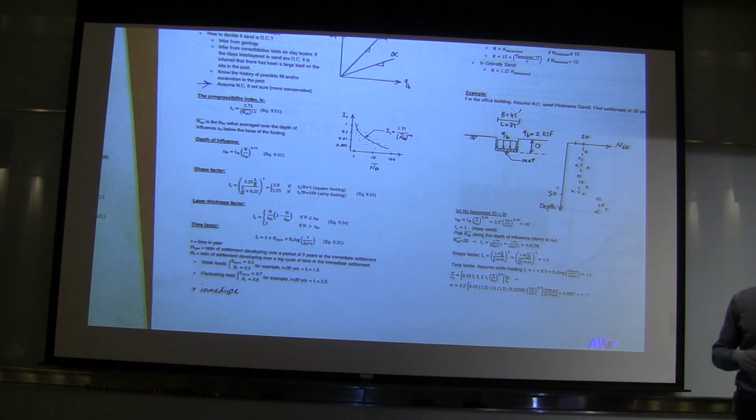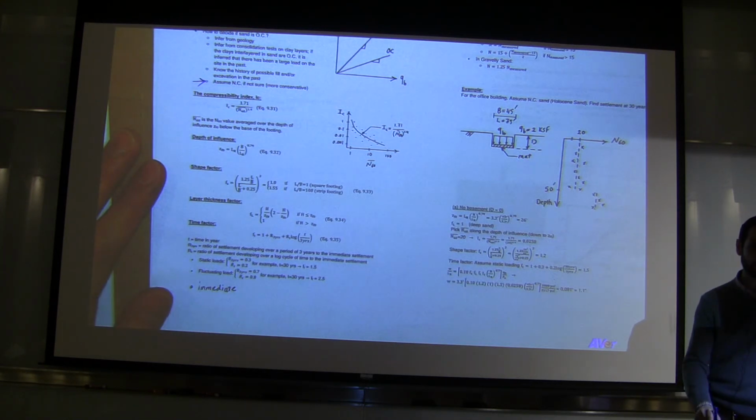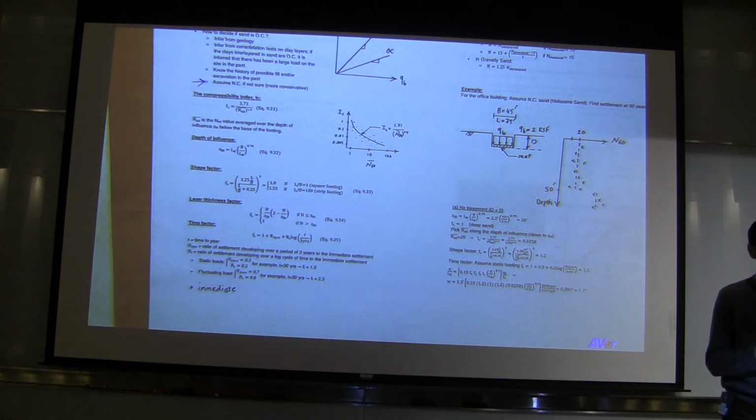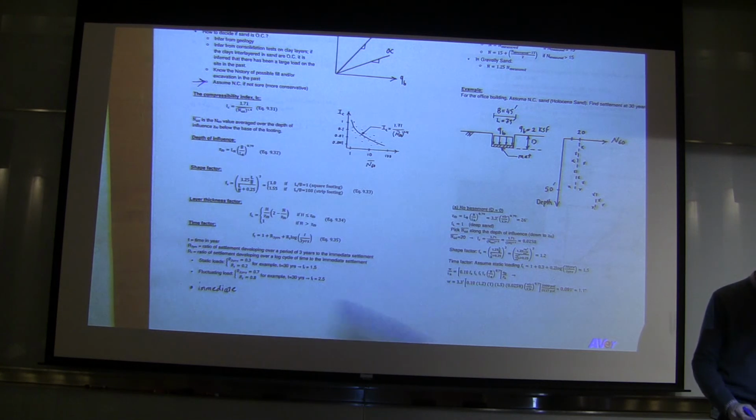So let's say, just for an example, we have a case where we have 10 kips of static load and 10 kips of dynamic load. Then you can break your settlement calculation into 2 pieces. For the static part, you can use the static parameters, and for the dynamic part, you can use the other ones, and you can superimpose them, add them together.